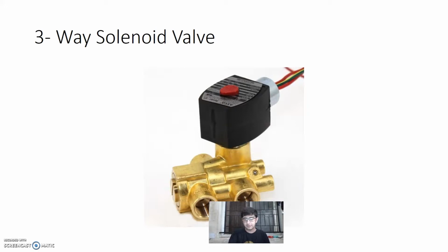Here, first the back portion of this outlet would be connected with the compressor, and the front portion facing us, which we can see in our slides, is for diverting the flow, whether we want to give the flow to the outward stroke or the inward stroke. You can Google what a pneumatic cylinder is. Here you can control your flow, whether you want it to go in this direction or in the left or right direction, right? So this is a three-way solenoid valve. It's useful many times.